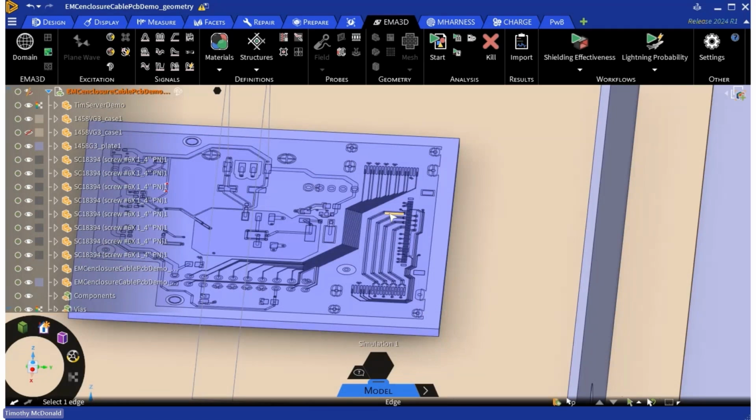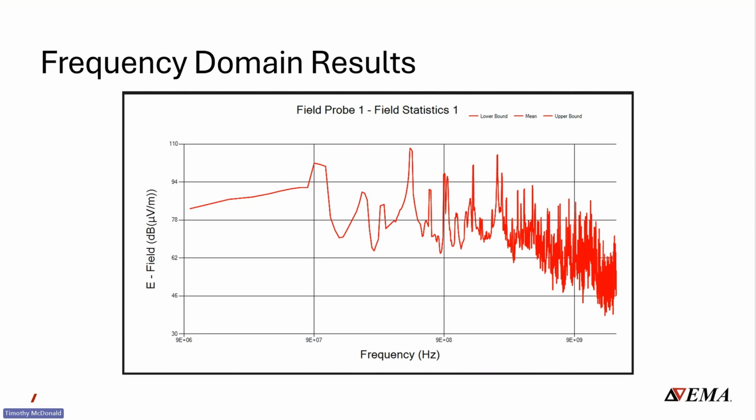Many types of board design software are able to import or export the EDB format that we can consume, and the tool will automatically assign the material properties: copper to the traces and ground planes, FR4 to the dielectrics. Then we're able to connect that using transmission line theory to harness cables, which can be shielded and unshielded, etc.